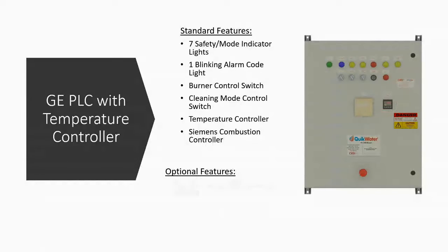It's also got an optional feature, another thing you will see on all of the QuikWaters. It's got the ability to put a transfer pump VFD in. This will control your pressure on your discharge. It allows us to keep a steady pressure on the discharge, which makes the unit itself a lot more efficient. It allows the unit to ramp up or ramp down as needed based on demand. This is something we offer with all of our QuikWaters.